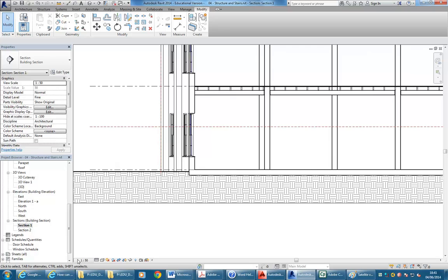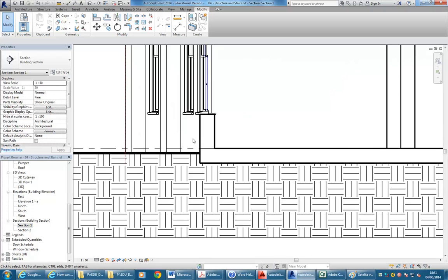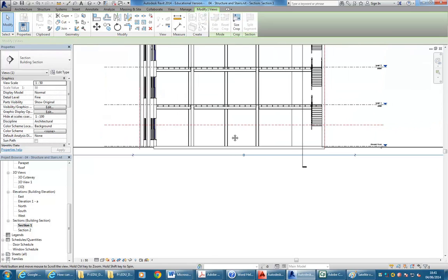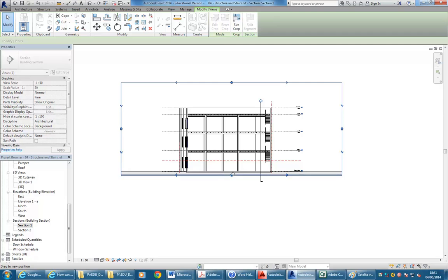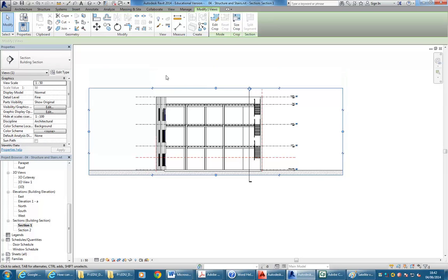Okay, so I've just taken the scale down a bit there, so it's got heavier line weights, and then you can see it's not looking too bad now. It's got the wall and especially the floor set into the ground. It's not perfectly showing the way the structure would be in real life, but it's good enough for an interiors project. You don't need to show all the detail, but you at least need to show that it's an enclosed space. And having the ground line is a good thing just for formatting in general, and the ground hatch. So by adjusting that crop region there, I control how much of that ground hatching to show. Going into the elevation views.